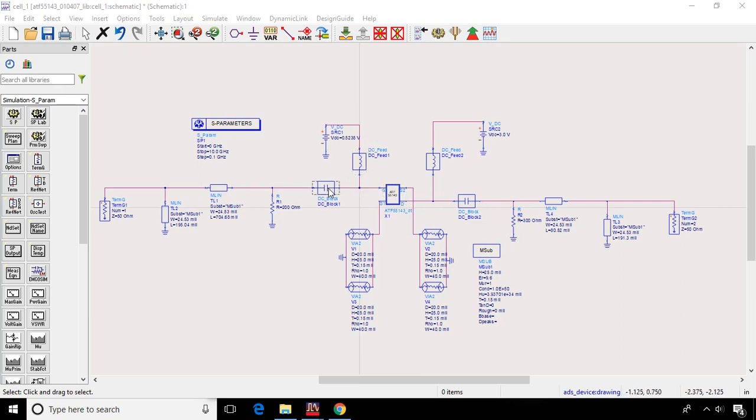For example, the inductor, the DC block capacitors, the resistors, they all have pins that have specified dimensions on them, and you need to figure out what those dimensions are, and those would be the pads for your PCB layout, and also including the PCB pads for the transistor itself.